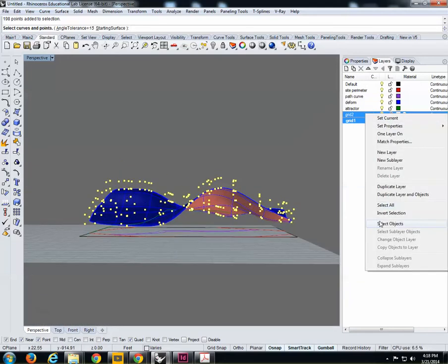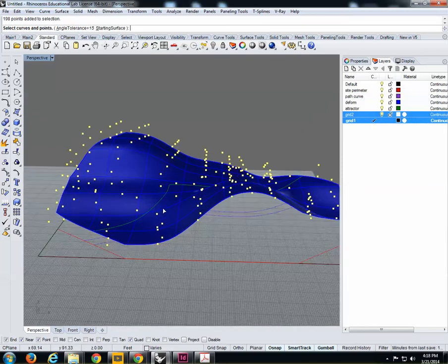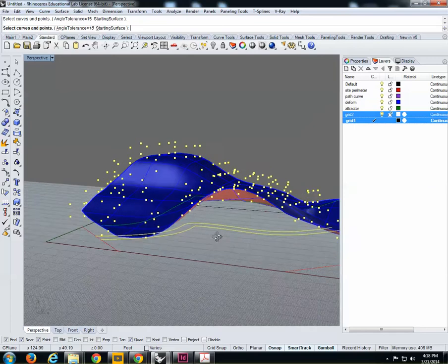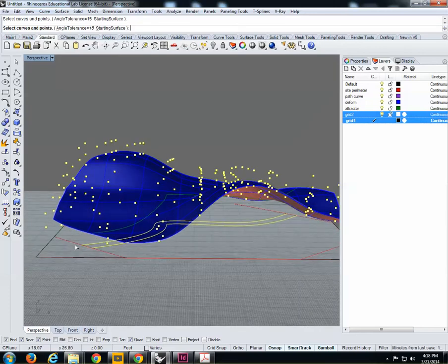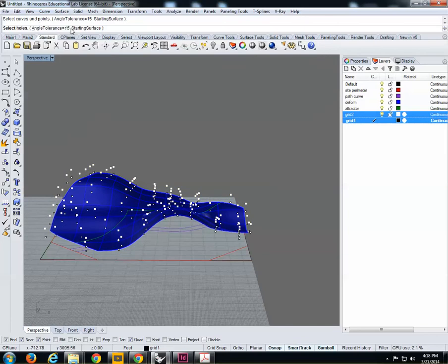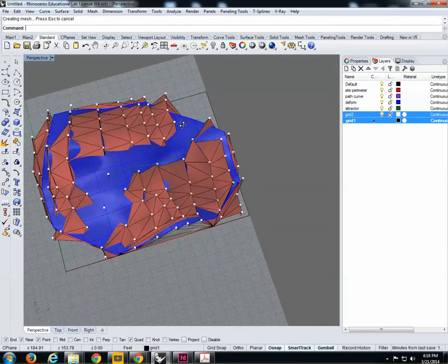So right click and select objects as soon as you have highlighted the layers. Then the instruction said, okay, select also your path. So whatever triangulation happens between the points will respect this path and leave it clean. And also select the perimeter of your side, so you start enclosing the side with triangulated facets. Enter. Now let's all just type enter here and accept the result, and this is what I get.